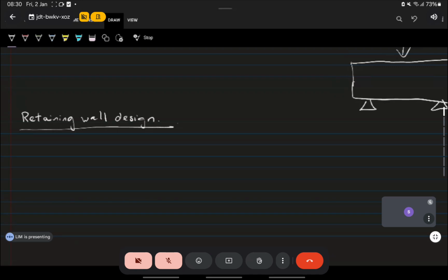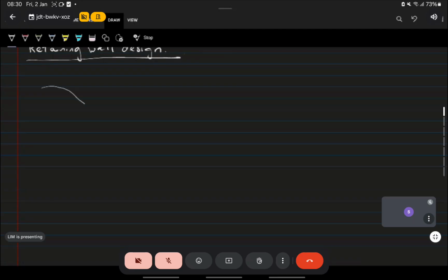In Sabah we've had heavy rains in the past, and it's caused landslides, things like that. Landslides are basically caused by unprotected slopes. So when you have a slope like that, why does a landslide occur? A landslide occurs when there is a slip plane that forms in your slope. Let's say that's your slope. When the weather is dry, a landslide doesn't occur. It normally occurs when there's water. Water is the biggest culprit in landslides. When it's dry, the slope is stable. But when it rains, the water